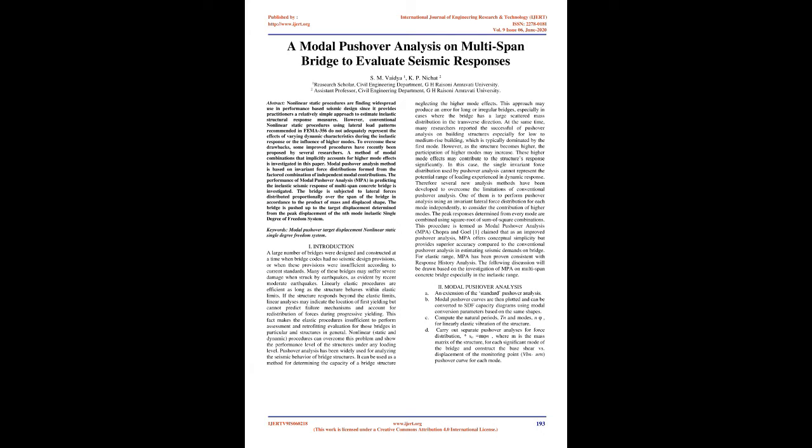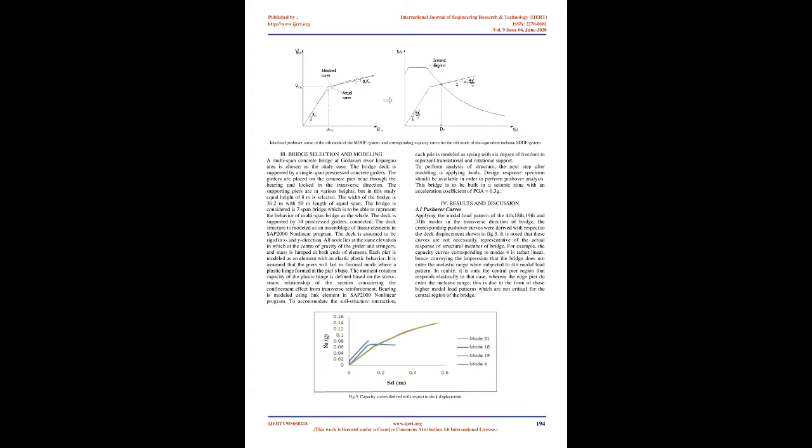However, as the structure becomes higher, the participation of higher modes may increase. These higher mode effects may contribute to the structure's response significantly. In this case, the single invariant force distribution used by pushover analysis cannot represent the potential range of loading experienced in dynamic response. Therefore, several new analysis methods have been developed to overcome the limitations of conventional pushover analysis.